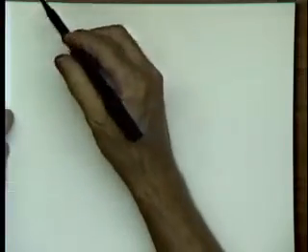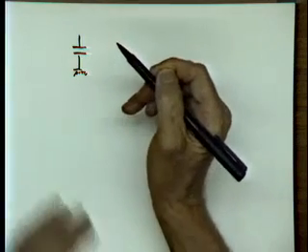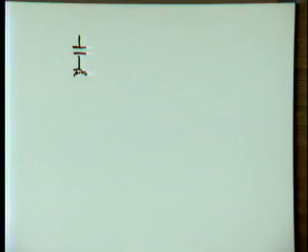So let's talk about transient analysis. Okay, so what we have is somewhere a transistor network driving a capacitor. Right? So for all the transient analysis, propagation delay analysis, what we're going to do is take our capacitors, which can come from many sources. We'll talk about that later. We linearize them and we lump them together into one load capacitance. That makes life easier. Rather than having a very complex network with a lot of resistors and capacitors, now we would like to have a network with one resistor, one capacitor, or one current source and one capacitor.